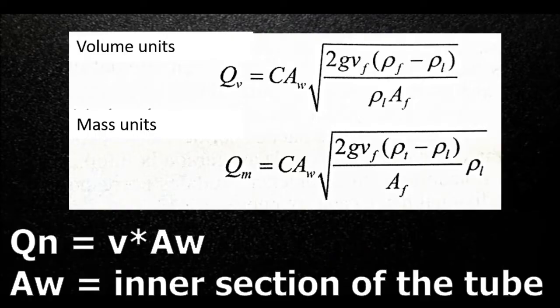Being a diaphragm with a variable orifice, the rotameter will have a discharge coefficient that will encompass the uneven distribution of speeds, fluid flow contraction, pipe broadness, etc. For this, we add the term C to the previous expression. Then, the volumetric flow rate and the mass flow that pass through a rotameter are calculated with these formulas.